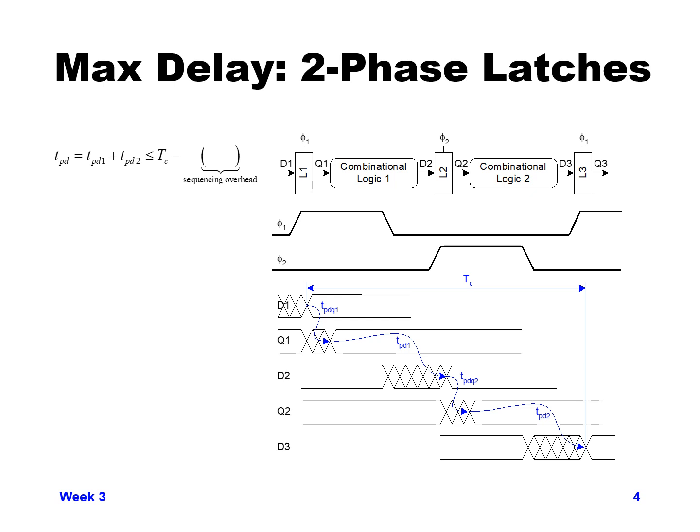So we'll go straight through that latch and get a propagation delay through latch 2, TPDQ2, and then we have the delay through combinational logic 2, TPD2. If we get to latch 3 around the time that latch 3 is opening, then we'll just flow straight through latch 3.